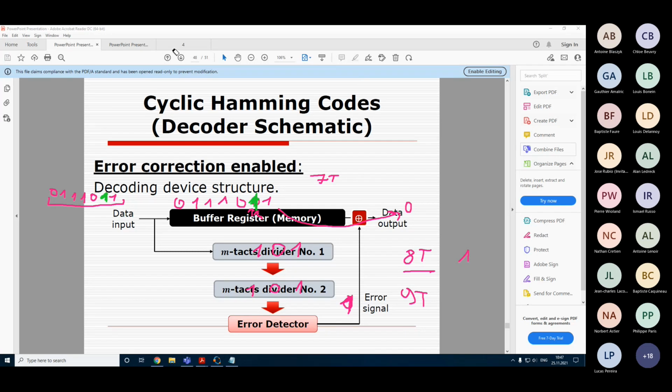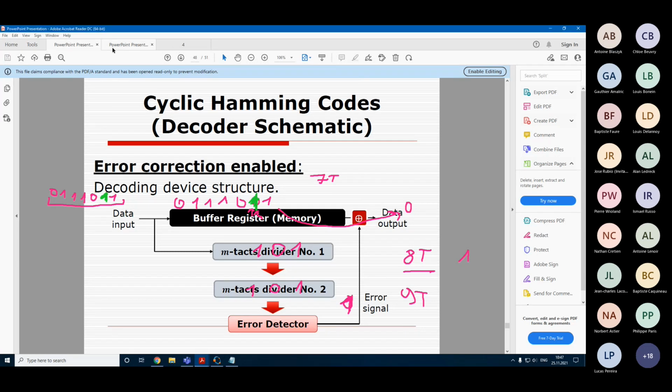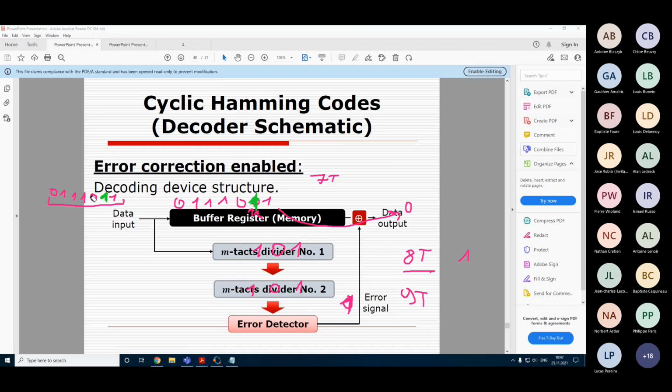And the trick is that the remainder for error in this position was 111. So at takt 8, this remainder will be 111, which doesn't correct any errors, because only remainder 101 triggers the correction.